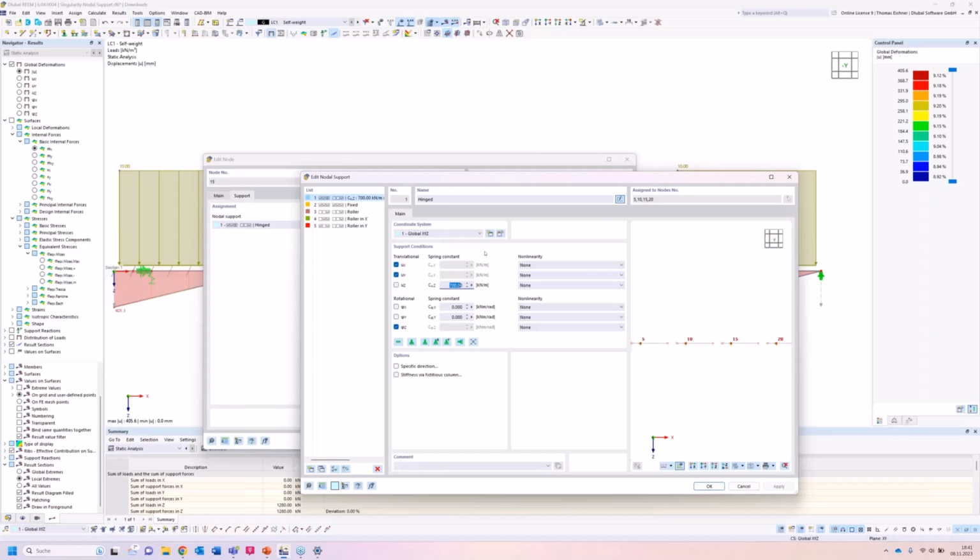You can also just go for the spring constant value, but here, like I said, there are a lot of insecurities in material, in everything. That's why there's this factor for concrete of 1.5, so a 50% safety factor for the material.